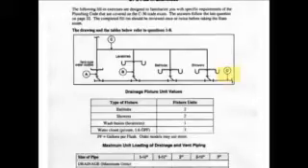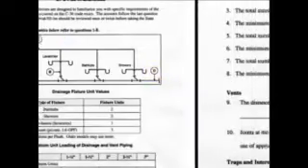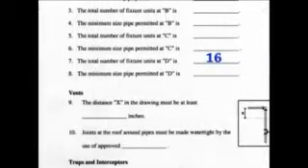So we know from the problem that we just did that the lavatories, the bathtubs, and the showers add up to 10 fixture units. And we know from the earlier problem of the water closets that those are 3 each. So that would be 6. That would be a total of 6 plus 10. We would have 16 fixture units on the D area pipe. So the answer for 7 would be 16.